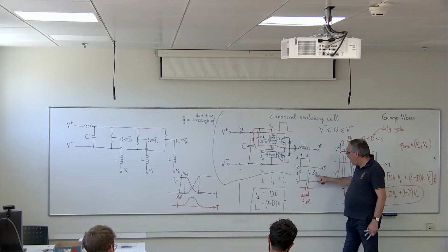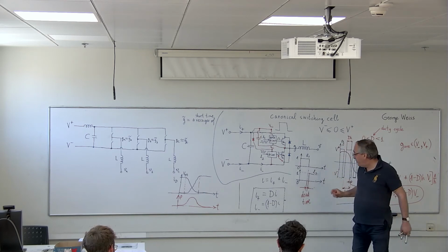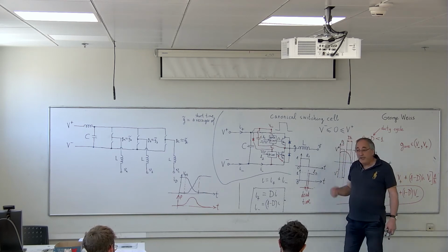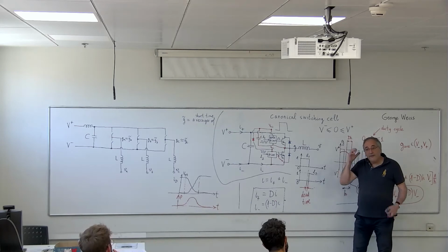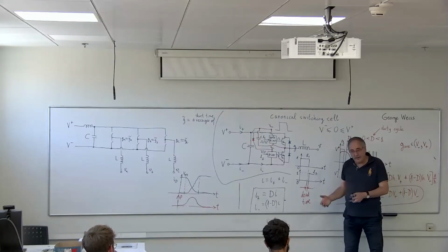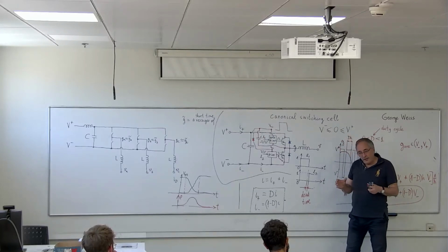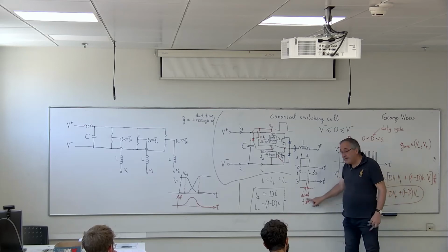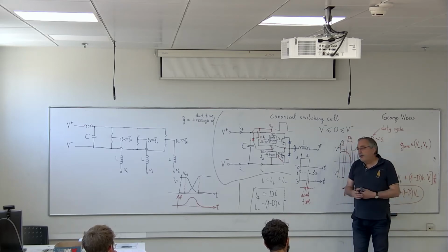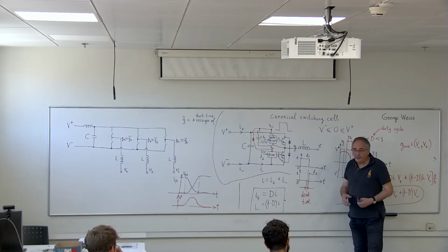When you disconnect L2, I mean the second switch, and connect the first switch. So on both sides of the switching, you have to allow this dead time. And the PWM generator, so you have this circuit, which is a PWM signal generator, which very often is part of your processor. So that is already programmed to allow this dead time. And you can also adjust this dead time. So it's one of the parameters in your program to adjust this dead time.